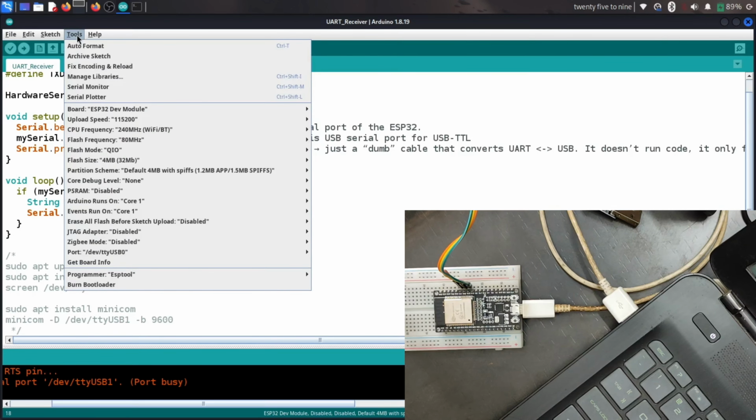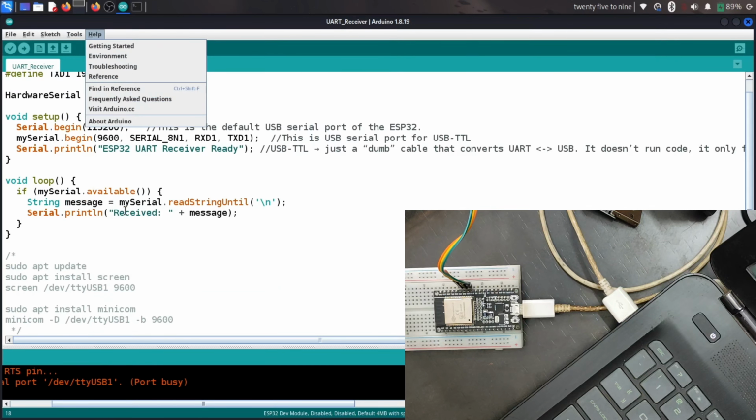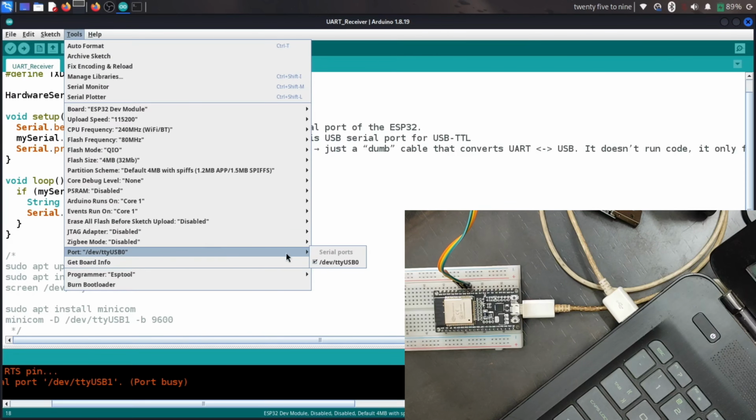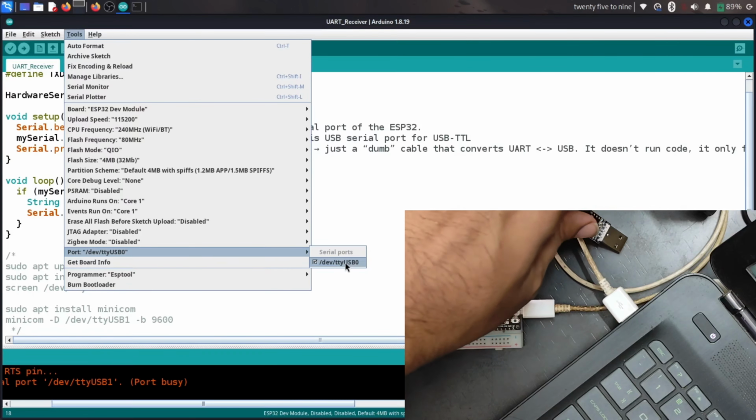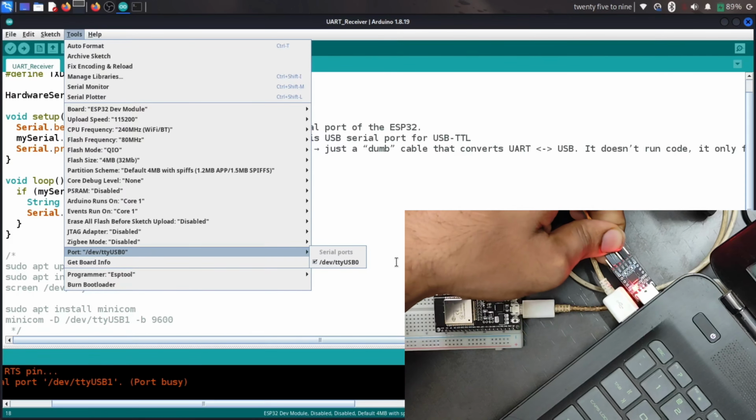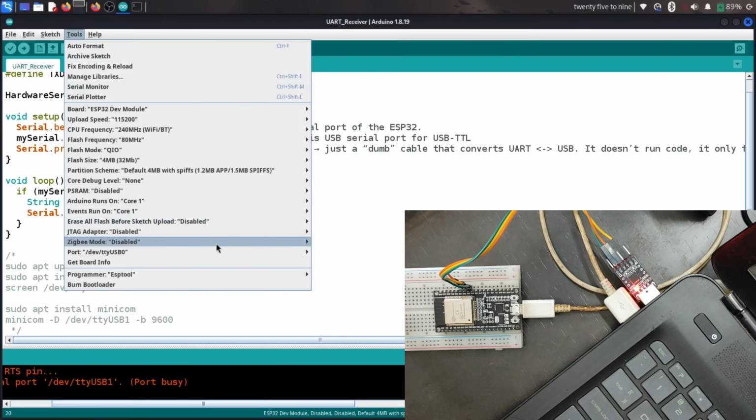First, before we talk about the message information, we need to tell you something. Here we have the serial port. We need to change to USB 0, right? I will connect USB-TTL 1 now. It's not updating. Yeah, it's now updated. This is for USB-TTL. This is for USB ESP32. If you need to update data, we must select this one. If we want the ESP32 in a second device, we need to select this one. But since we are using a TTL converter, we don't need to select this one, okay.